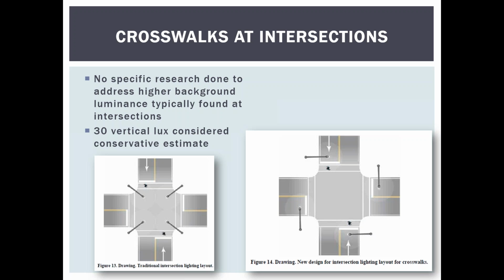Does that make sense? Yeah, that does make sense, and that is a concern, because while there were minimum lighting levels required for the flasher on the rectangular rapid flash beacons, there really was no maximum level, and there can be such a thing as having too much light. In other words, distracting from the sign and distracting from the pedestrian.